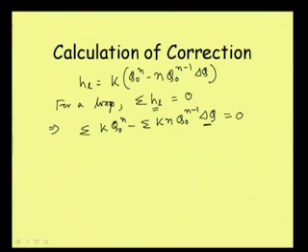So, delta Q is constant for the members of a loop. When we are talking about summation, Q0 and K will be different for each pipe, but delta Q is the same. So, we can take delta Q common out of the summation and write like this.